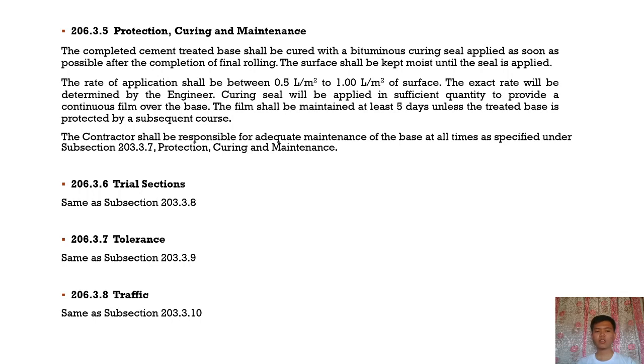And last is the traffic. It is the same as subsection 23.3.10, which stated that the contractor will not be permitted to drive heavy equipment over completed portions prior to end of 5 days curing period, except pneumatic tired equipment required for construction of adjoining sections.